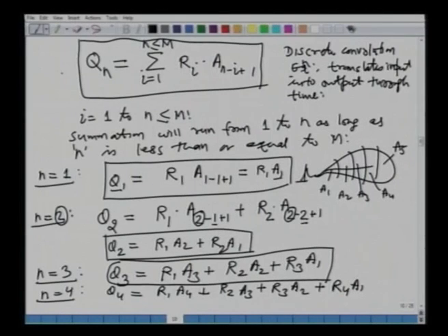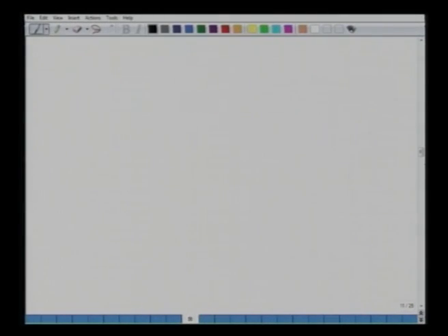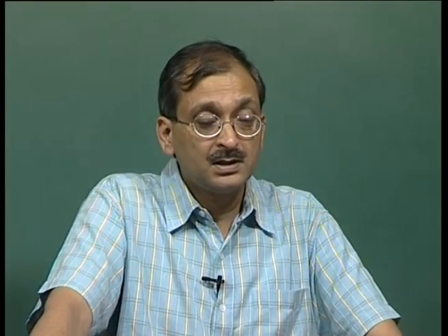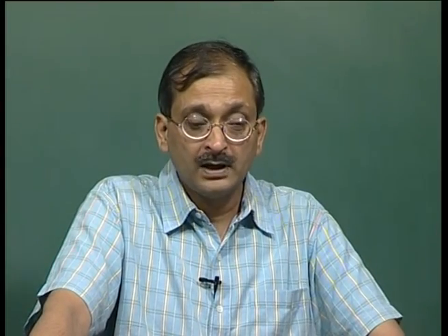So, you can find the direct runoff hydrograph, and it would look like this. You have the different times and then you have q, and these are the different ordinates you have calculated: q1, q2, q3 and so on. So, you see that the computation of the direct runoff hydrograph using the time area diagram is a very simple process, using this discrete convolution equation.